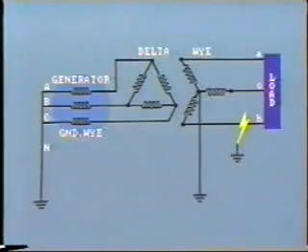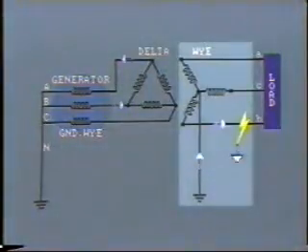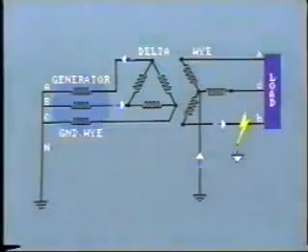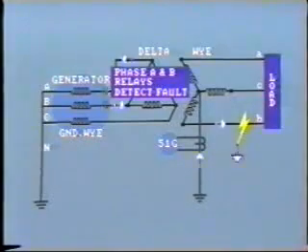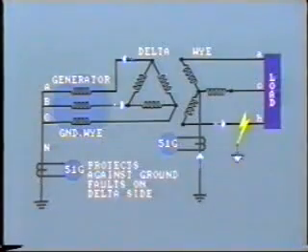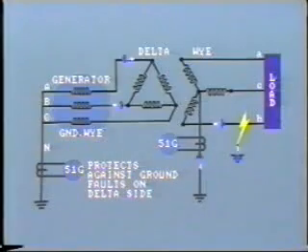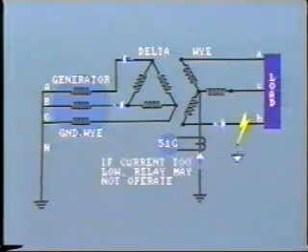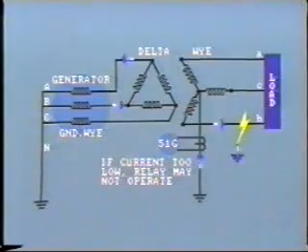With the Y side grounded, ground fault current would flow in the faulted phase of the Y winding and would be transformed into the delta winding as shown. Note that the phase-to-ground fault on the Y side manifests itself as a phase-to-phase fault from the delta side. Thus, generator phase A and phase B relays could detect the fault, as could an overcurrent relay in the neutral of the transformer. An overcurrent relay in the neutral of the generator would protect against ground faults on the delta side of the transformer. Note that if the level of fault current is too low, this relay may not operate at all.